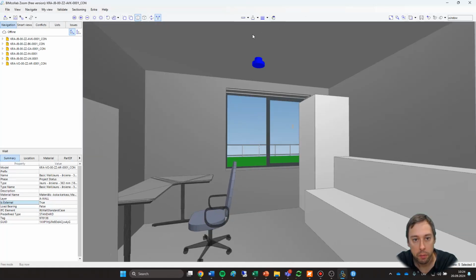So here in the middle are some other tools you can use. So the first one is the dimension tool. It works fairly simply. There are basically no other options, just one dimension tool. Press it, and you can snap to different intersections, planes, or just simply points on any plane, and then make a measurement in this 3D environment like this. You can make multiple measurements if you want,